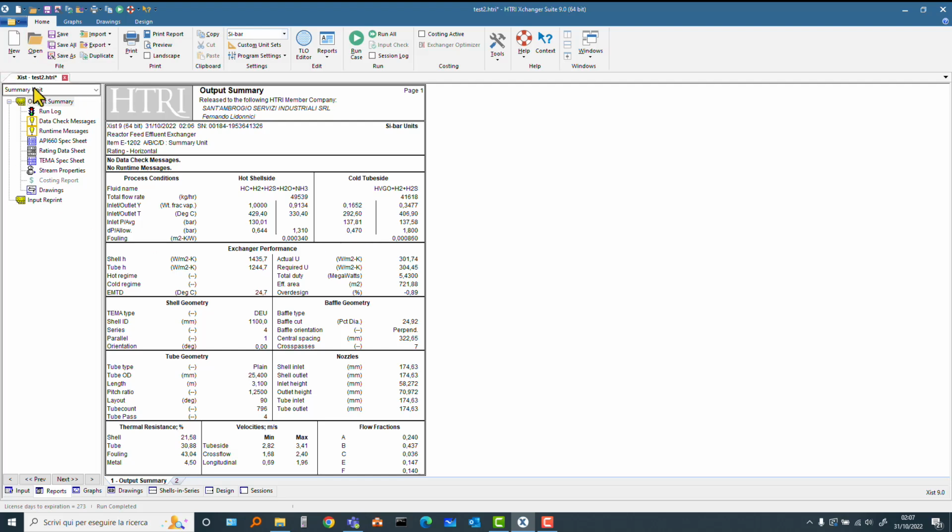So this is the summary unit, and this is the pressure drop of all the parallel shells. So it's 0.47 against 1.8. So there is space if we want to increase the tube side coefficient. On the shell side there is also space, but what is the deciding coefficient?